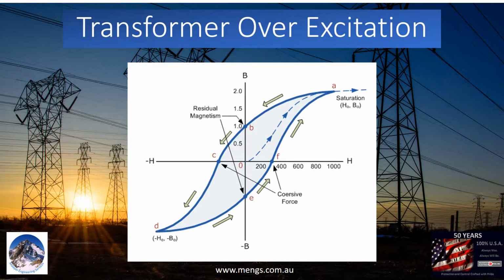Eventually, at a certain external magnetic field, the domain walls have moved as far as they can, and the domains are as aligned as the crystal structure allows them to be, so there is negligible change in the domain structure on increasing the external magnetic field above this. The magnetization remains nearly constant and is said to have saturated.